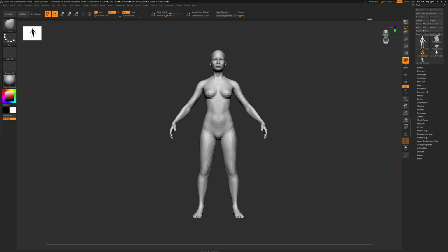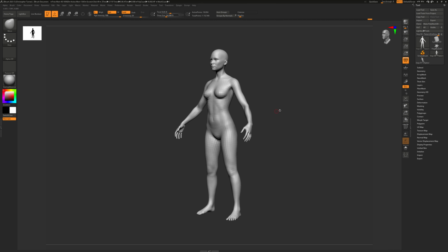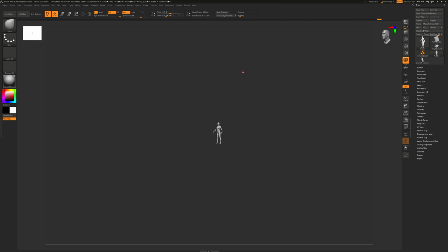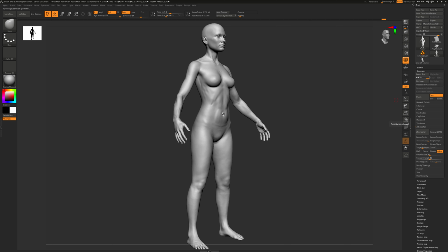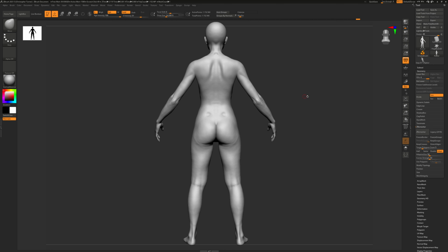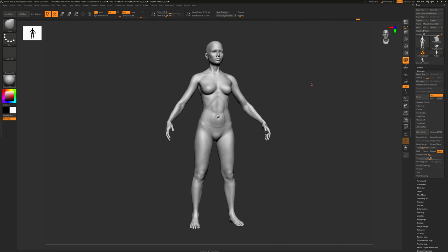And now inside of ZBrush, in order to rescale her in ZBrush, I'm at my lowest subdivision level. I'm just going to go to import, and I'm going to grab that avatar, and it will scale her accordingly here. And all of my subdivisions are still there. So she's actually completely scaled up the way that I want her to, taking all of that information and detail along with her. So brilliant. Now that I've got that done, I could save this file, and she's now to scale.